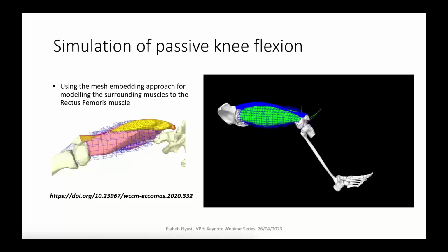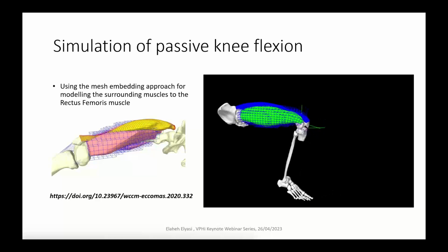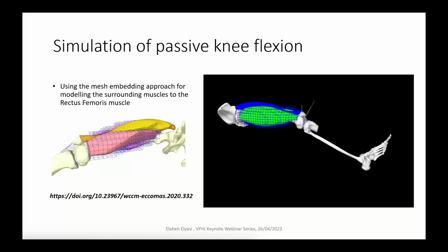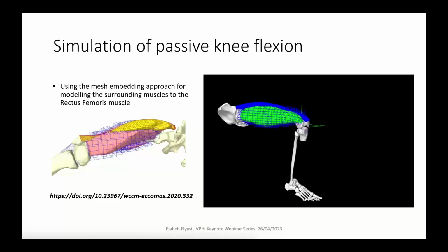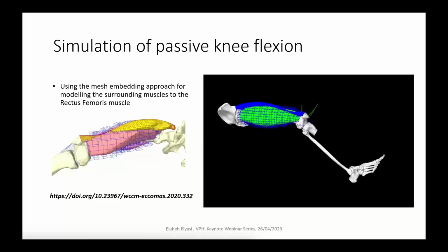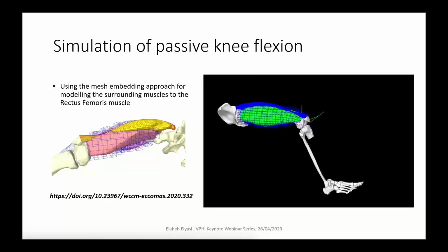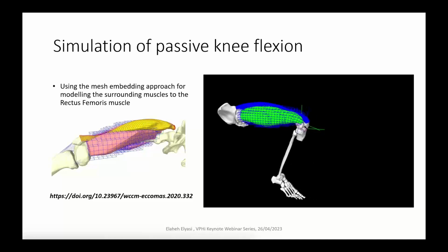Another thing that we tested was also to use muscle surfaces embedded in a coarse FE mesh for the 3 vastus muscles. And in that way, we could still include the effect of contact forces between the volumetric muscles that are compacted together in the thigh. But we could reduce the computational time of the model to 1/3 of the fully FE model that you saw in the previous slide, with relatively small sacrifice on the patellar kinematics and stress distribution that we were computing for the rectus femoris muscle.